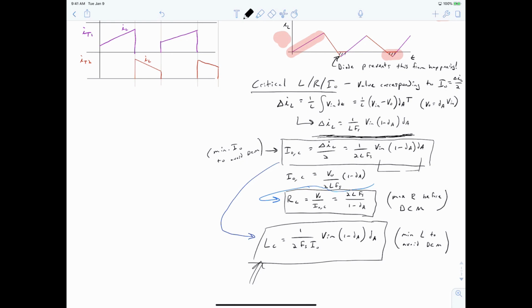The inductor value is often chosen to suppress ripple current to a certain value, but a good rule of thumb is to ensure that the inductor is at least 3 times the critical inductor value for the rated load of a given design.